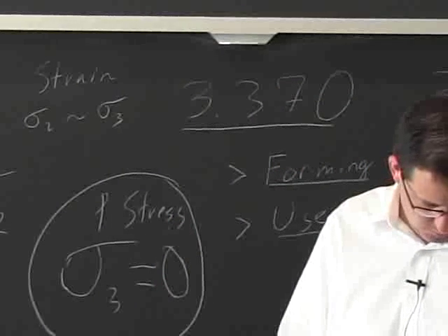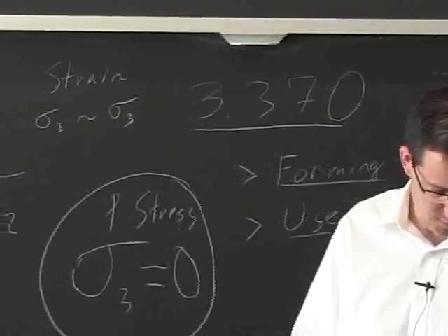All right, so this is a view through the thickness of that plastic zone, showing that near the edges, you are allowed to reduce the thickness. It's a free surface. So on the free surface, you can't have tension in the thickness direction, and therefore it is not a triaxial state. It's this state right here, plane stress. But as you go towards the center, now the material that's stressed highly around the tip is constrained by this mass, this elastic mass of material that's around it, and that's why it doesn't shrink.